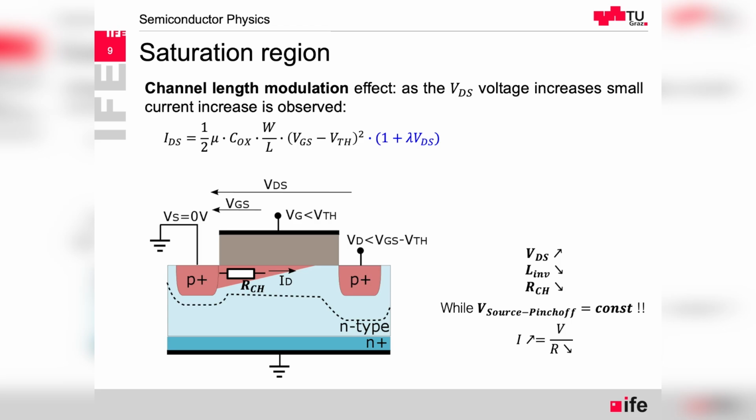Let's go to the opposite side, not NMOS but a PMOS transistor. So we are decreasing the source voltage, and at some point it's lower than the gate, and also the difference between gate and drain is such that the drain to gate voltage becomes smaller than the threshold voltage.